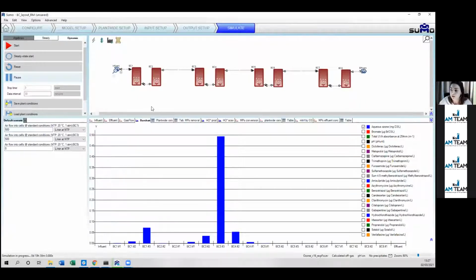So what we did now, splitting the dose in two bubble columns, is letting the ozone react first with the organic compounds, the water matrix, in the first bubble column, and in this way we allow ozone to increase its lifetime downstream.